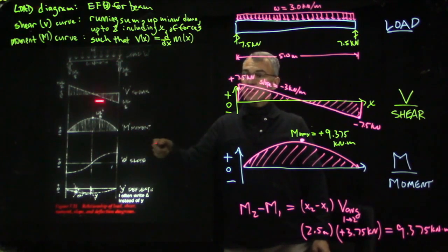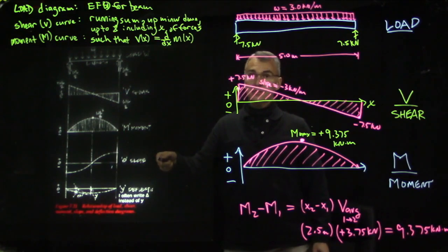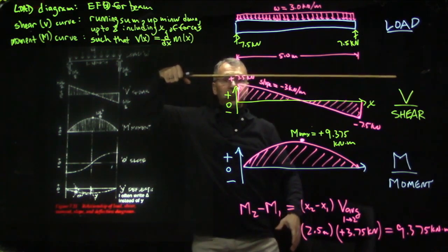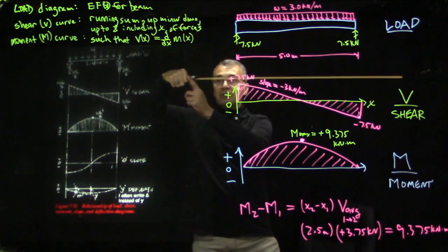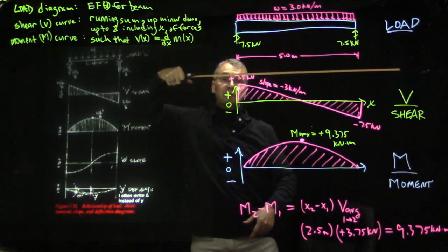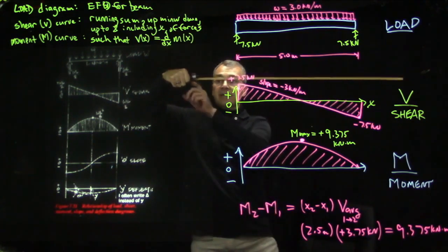Then this moment diagram M equals the integral of the shear diagram V. And when you integrate, there's a constant of integration, and that constant is determined by what's happening at the ends. Usually at the end there is 0 torque or moment, though an exception to that is the end of a cantilever that is attached to a wall, since that attachment can and does exert a torque or moment on the beam at the point of attachment.